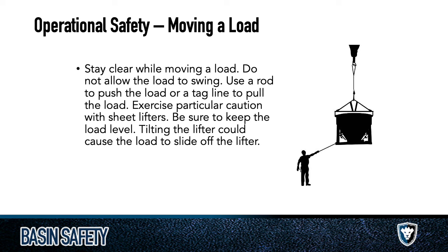So when moving the load, I already kind of talked about this. We want to make sure that we stay clear. For me, it should never be a situation where it's like 5-foot tag lines. Obviously the tag line has to meet the industry standard, and you don't want 100 feet of tag line behind you. I can get that. But you also don't want to be barely holding on to this thing, looking like a little kid holding his dad's hand walking down the street.